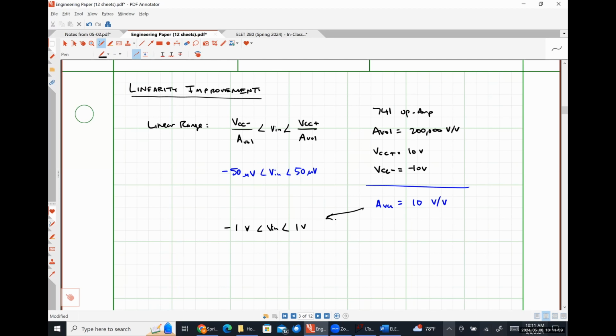So effectively, employing negative feedback makes us significantly less likely to put our device in a saturation position where our output does not change from a subsequent change in input. We obviously still have to pay attention, which is why supply voltages and all that kind of good stuff are so important, depending on what the gain you're trying to achieve with an op amp circuit is. But again, relating stuff back to stuff we've seen in previous classes, this is a pretty darn good explanation of why negative feedback improves the overall linear system.